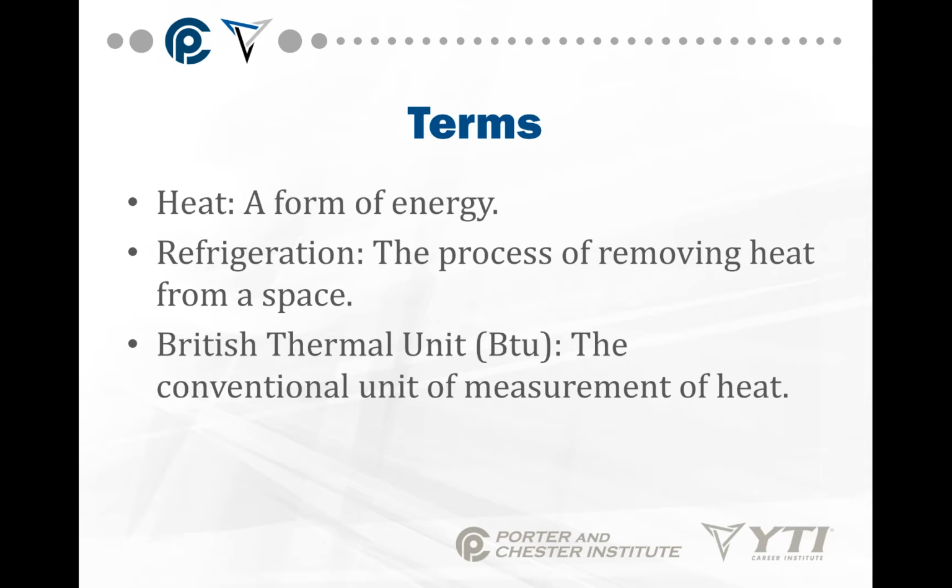First, heat. It's a form of energy, okay? It cannot be created nor destroyed, but it is always there, either as heat moving from one location to another. Heat moves from hotter to colder, and refrigeration is another term. It's a process of removing heat from a space. We need to remove it from a space where we don't want it and put it into a space where we really don't care if it exists, or a space where we want it. That's the process of refrigeration.